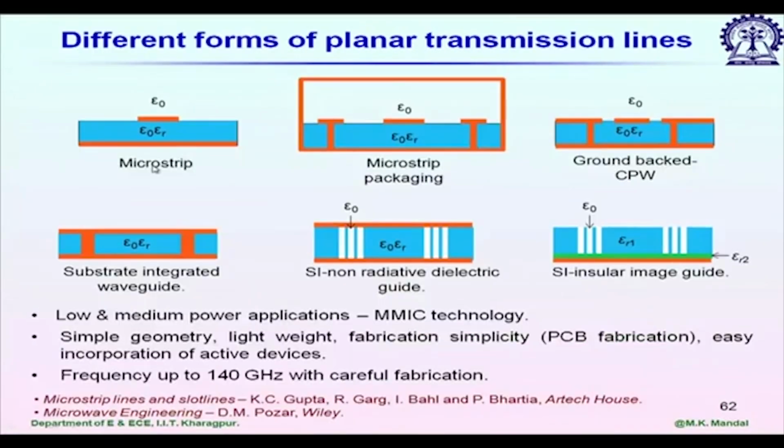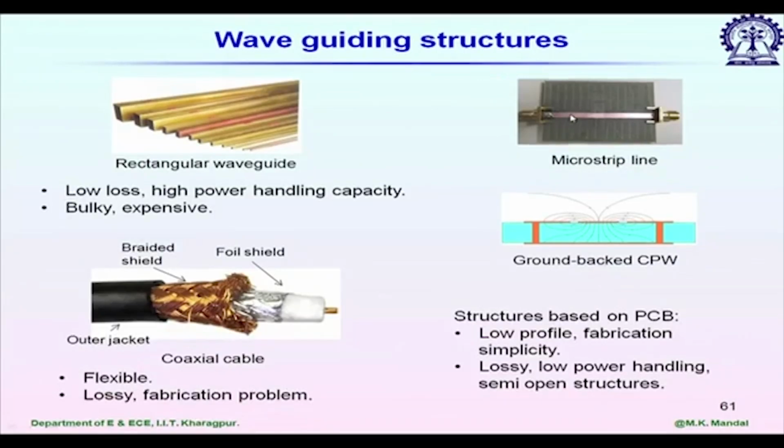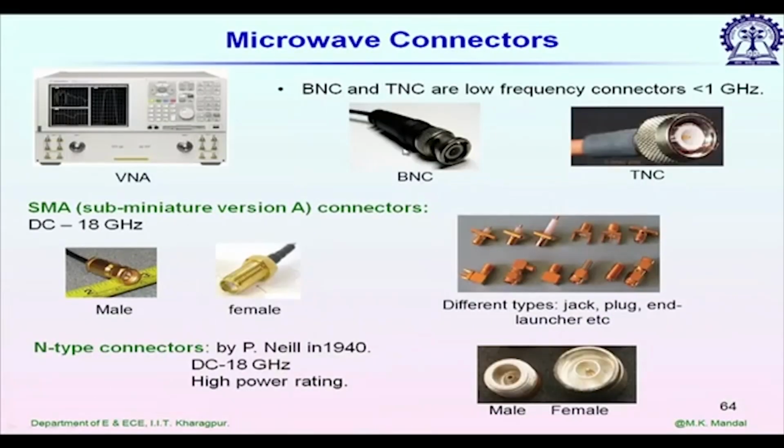Adapters, here we have already seen one. You see, this is the microstrip line and this is called an adapter. It will change coaxial mode to microstrip line mode. So, we are using these adapters for measurement purposes. Now, we can easily connect our coaxial cable to the left hand side or right hand side for measurement purposes. One end of these adapters is then always a coaxial line.